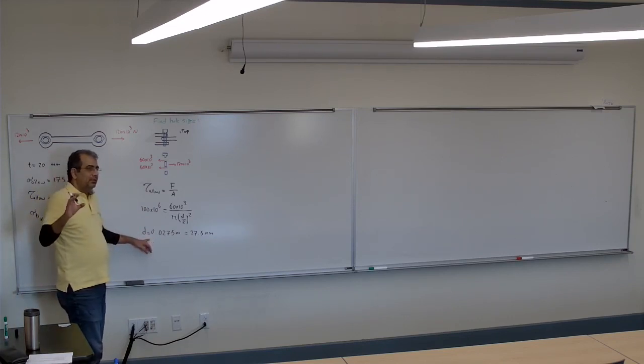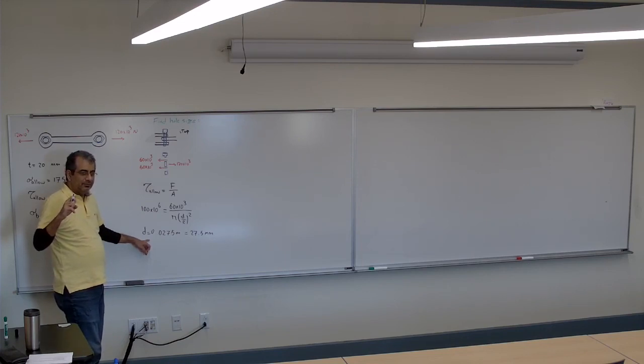So look at it this way. If I make the hole bigger, is it going to make it worse or better? We'll have to adjust everything, but if you make the hole bigger, then normally it would be stronger, because you're using a bigger pin, technically.